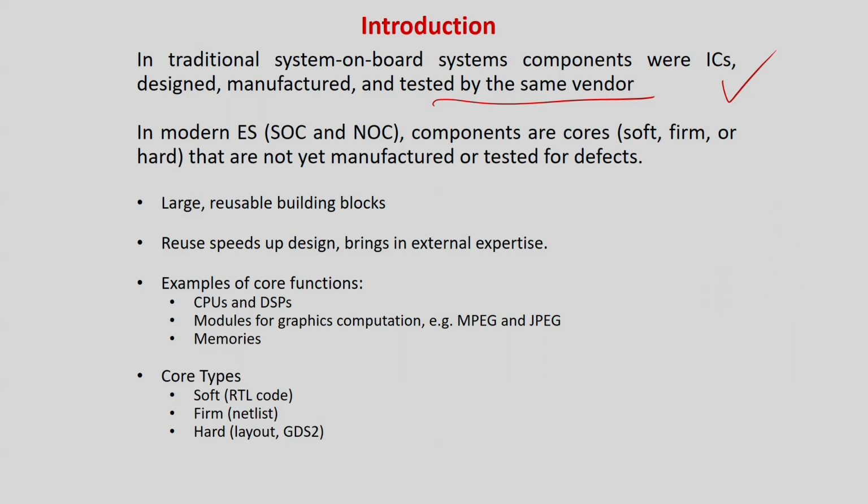To cut the long story short, in case of board based design, PCB based design, I can take much more ad hoc decisions, because I was actually purchasing chips and doing soldering, which is much simpler than doing a fabrication. In fabrication, everything should follow a protocol or a standard. So, in core based embedded systems testing, to access those internal pins, there should be some kind of standard, which allows a particular way of accessing or controlling these points. So that is one more important aspect we are going to look at in this lecture: in core based embedded system testing, what are the ways we can put some points in the interconnection of your cores and how we can access them.